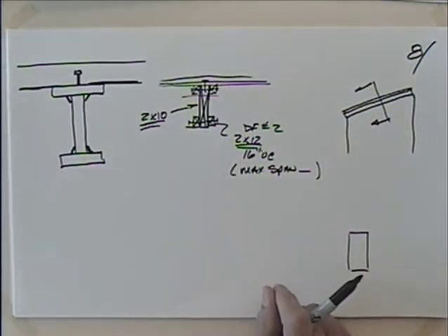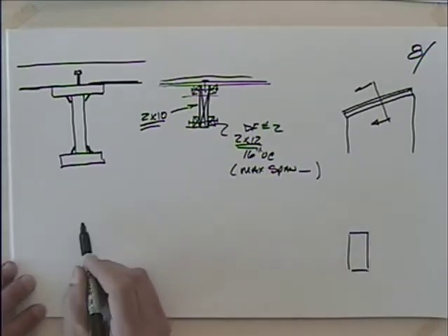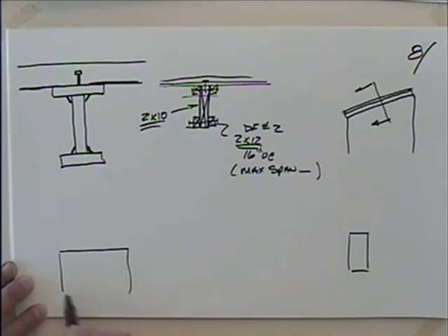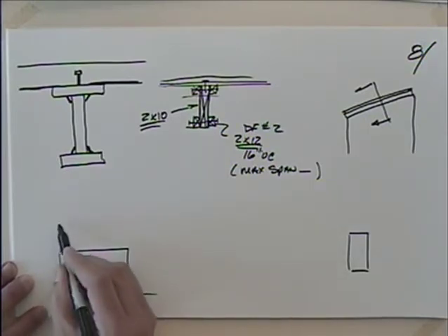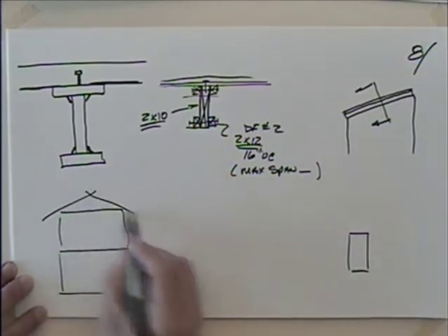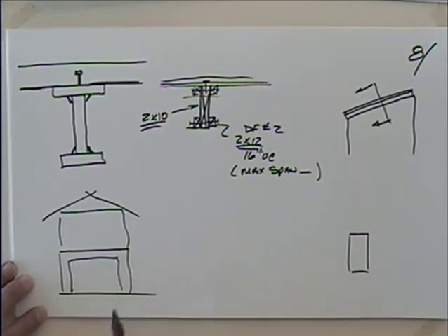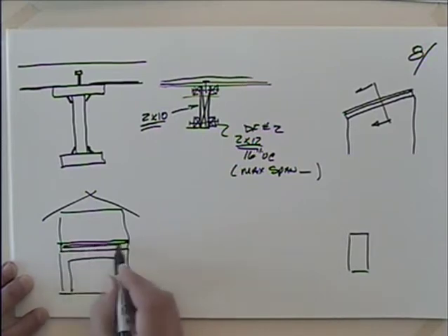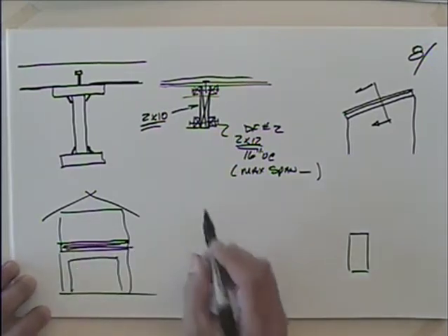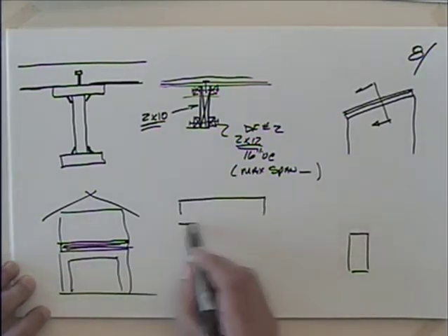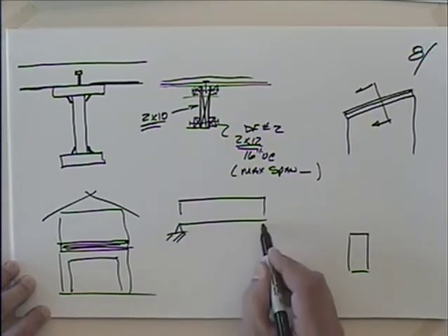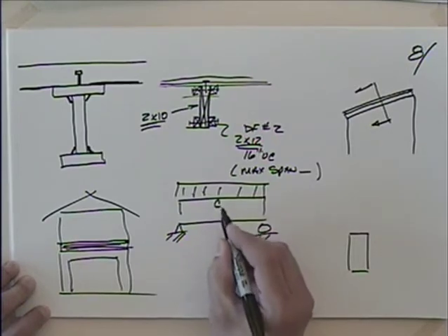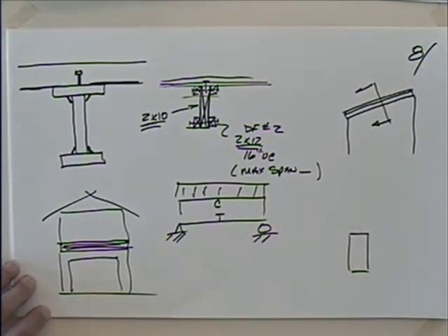well for that solution. The other thing sometimes you run into, you get these houses where you have a garage like this, and then they build the house up over the top like that. You got the garage door here, right? And usually you end up with a large beam in here, okay? And usually it's a great big glue lam beam. And with glue lams, if you look at a beam going back to bending, with loading like this, you end up with compression here and tension there, right?